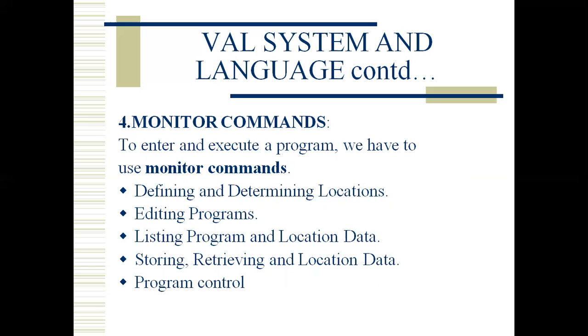If at all the dimensions need to be changed, x, y, z values, or the geometrical values, or circular interpolation values, either at the theta level or the phi level, those can be edited in the programming. And not only the geometrical strategies, but also the movements towards the left, towards the right, or towards the straight path, or the contour position, cylindrical positions, clockwise or counterclockwise, and theta with respect to the positive axis and the negative axis, whatever the condition is. Those also can be edited.